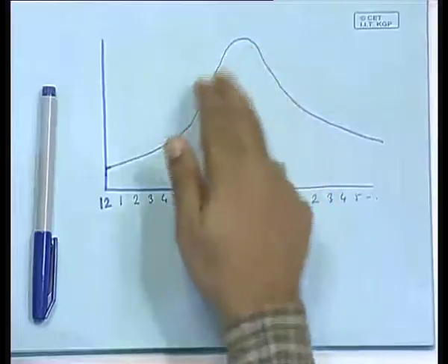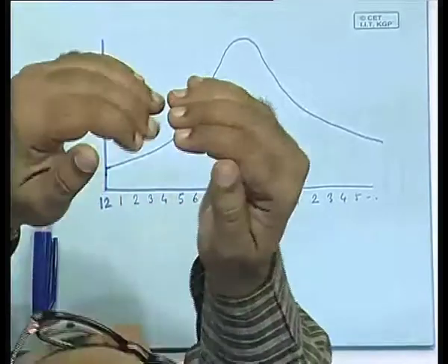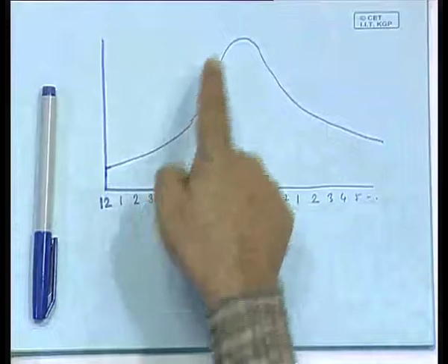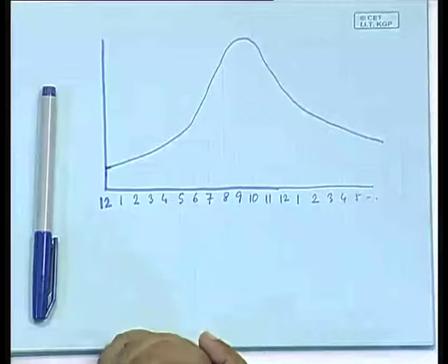So this variation, it is rather difficult for big power plants to take. Big power plants normally can work more or less at the same power level, and small variations are allowed, all right, but not much. Relatively smaller power plants can vary relatively faster, obviously, because the size is smaller, but nevertheless there is a limitation to it. So meeting the peak load, meeting the whole varying load demand is normally a problem. How to meet that problem?